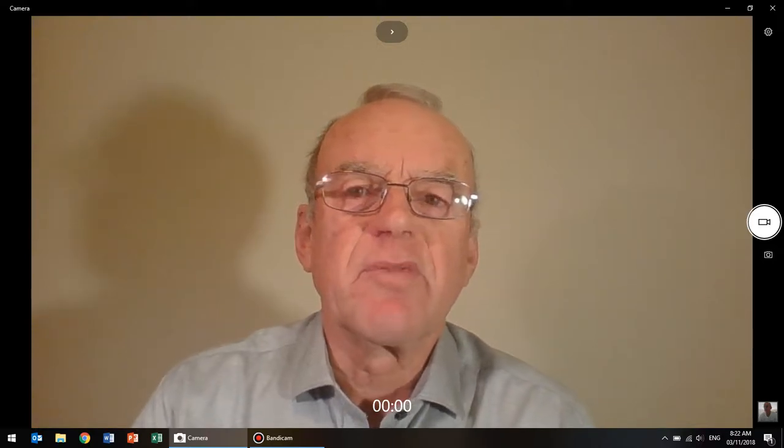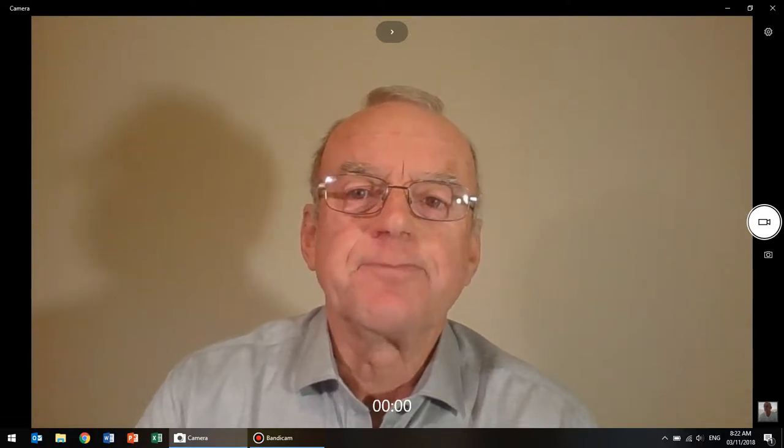Hi, I'm Don Armstrong. This video is the second of our two parts on scheduling maintenance work, where we take the work order information from your maintenance computer system and prepare a detailed weekly work schedule for routine, non-shutdown maintenance work. This is for a typical maintenance crew in any industry or institution. The purpose of this is to ensure that the highest priority work always gets done first.